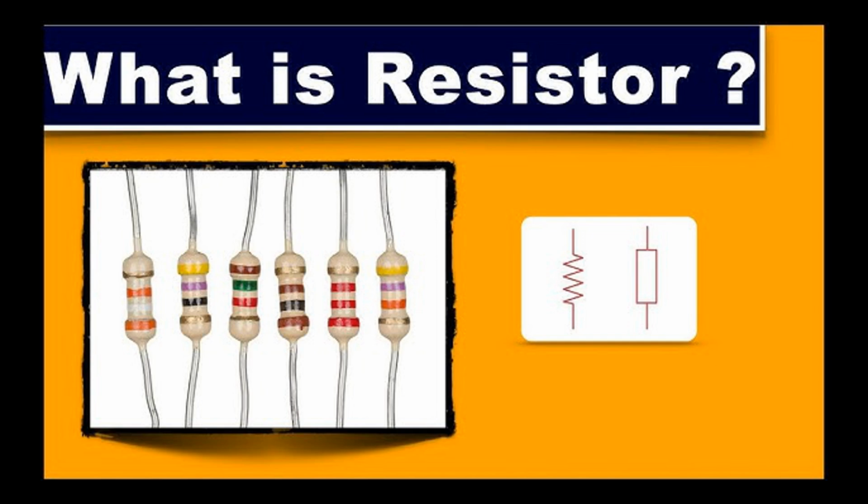3V over 0.02 A equals 150 ohms. Power rating: P equals 0.02 A times 3V equals 0.06 W. A 1/4 watt resistor would suffice. Current limiting through resistors is a fundamental practice in circuit design, ensuring both the protection and longevity of electronic components.